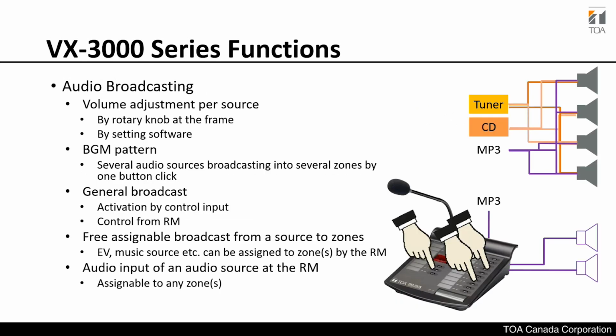So you can create general broadcasts. You can create BGM patterns that can be triggered. You can assign broadcasts to target a number of zones. That demo over there is programmed with three zones, 1, 2, and 3. So left to right, each speaker has an independent zone. I programmed 1, 2, 3 to be independent, each speaker on its own, and then 4, 5, and 6 are a mixture of them.